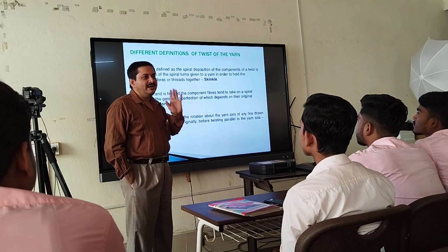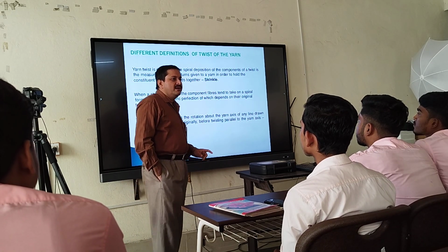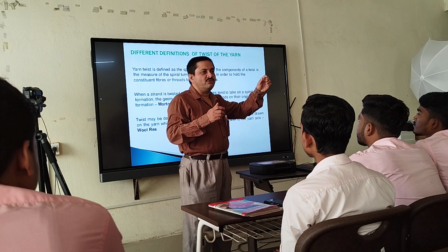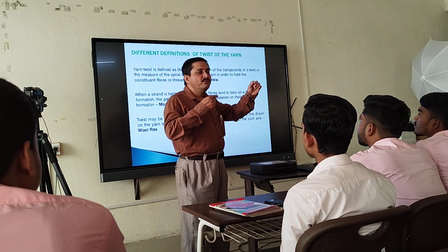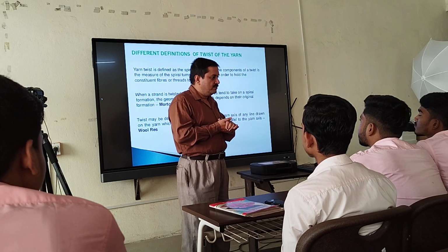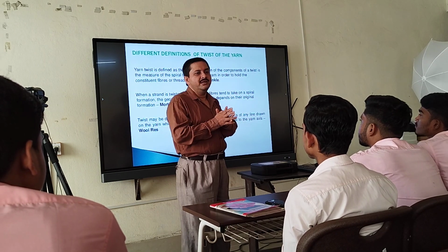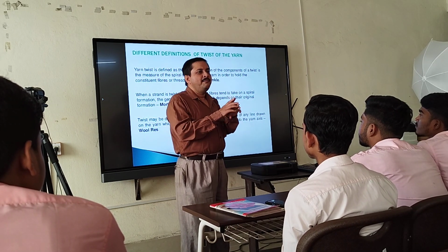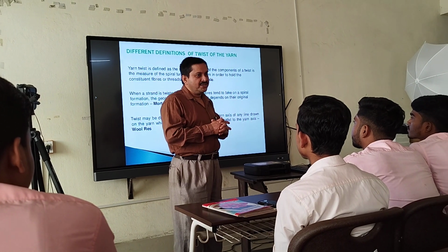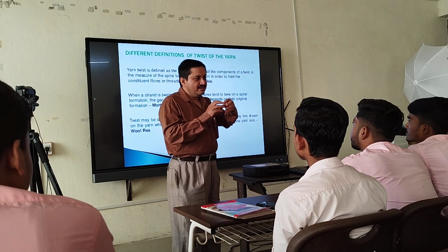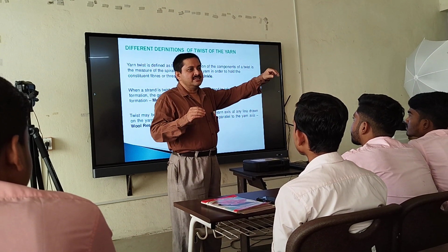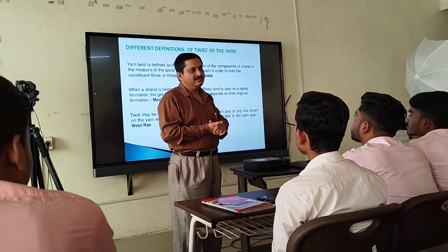But in a word I can say, due to torsional forces, what will happen? Your yarn or fiber will bend or spirally move. Due to the spiral movement, the fiber to fiber friction will increase, and ultimately they remain within a system and produce yarn.